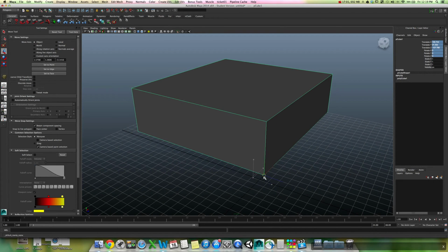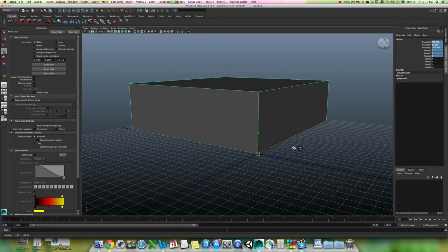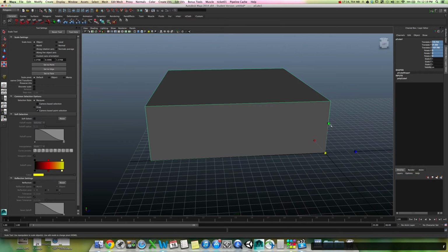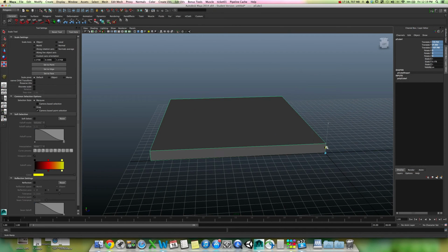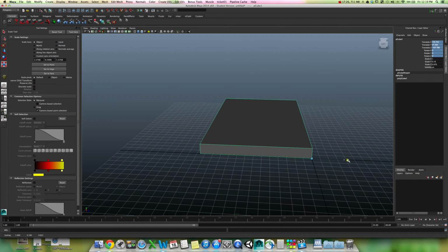And you can see it'll just basically snap and stick to that point. And we know that these are perfectly lined up, this corner and this grid, which means that my entire face on the bottom here is perfectly aligned to the bottom of the grid. Now, it's very useful for scaling, right? Because now I can scale it from the bottom. I don't have to keep readjusting the position.